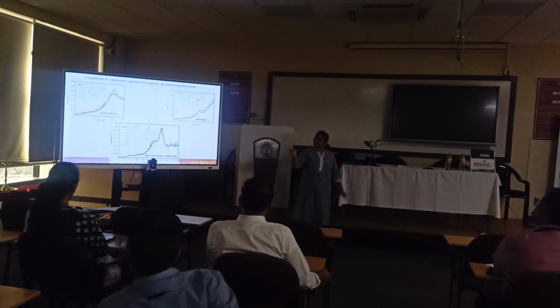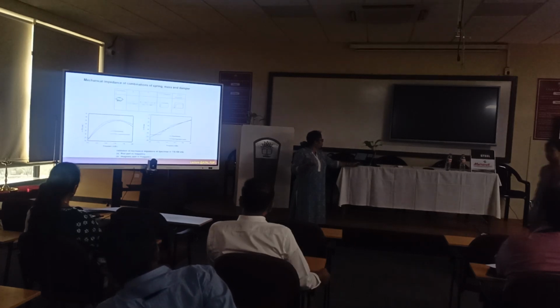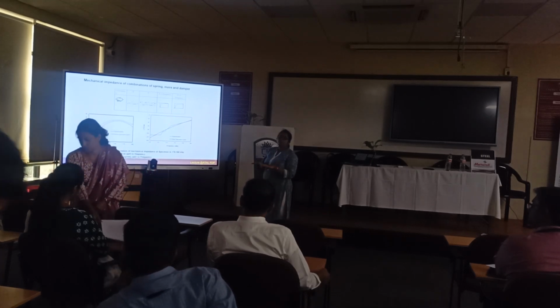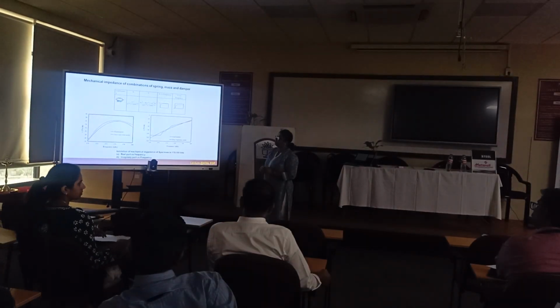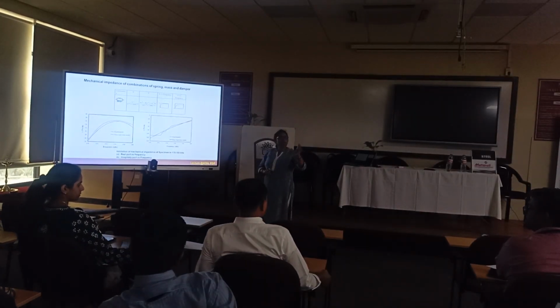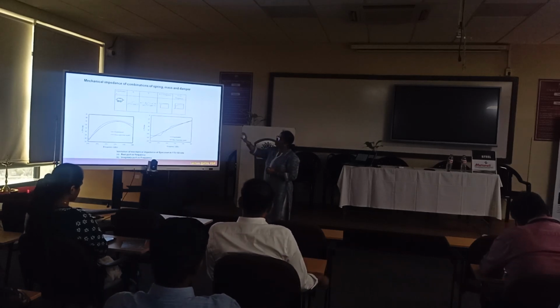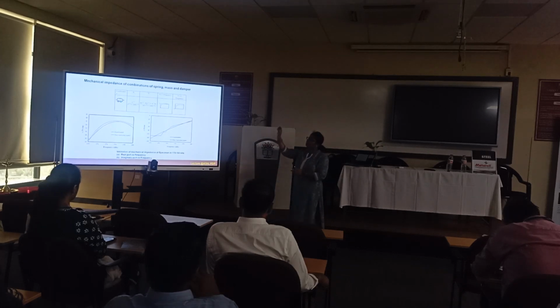You have a signal. This is the signal. It has a signature, and from the signature we also plot the conductance to give information in terms of structural information. Susceptance is also there, which is not being used. We want the conductance and susceptance to be reverse engineered to identify a mass, spring, and damper system. What exactly did I do? I took a signal and reprocessed it in terms of the Hixson model, where there are a lot of spring, mass, and damper combinations, and each combination has a certain pattern.